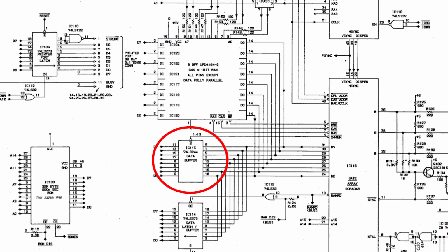Normally, bad RAM results in that gray square in the middle of the screen, but I suppose it depends on the bit and how it interferes with the rest of the computer. On the Amstrad CPC, bad RAM doesn't interfere with reading from the ROM because it's isolated by a buffer chip. But as soon as the initialization code in the ROM tries to use the RAM for anything, and I mean anything, like storing a return address for a function call on the stack, boom, it all goes wrong.